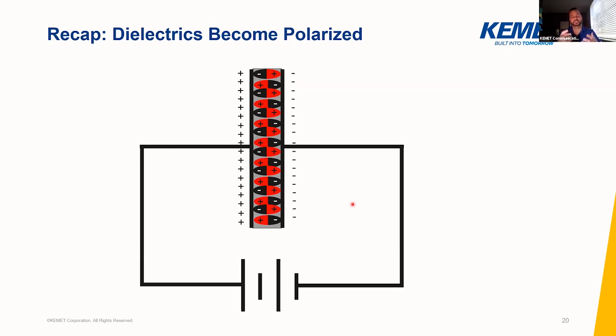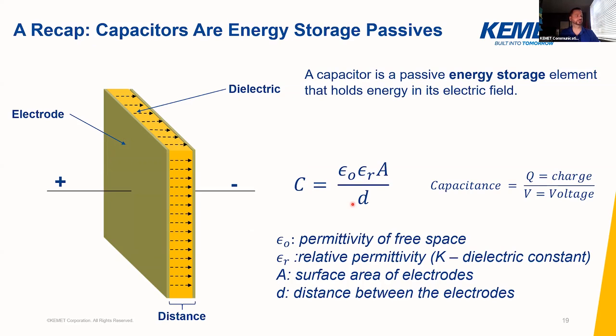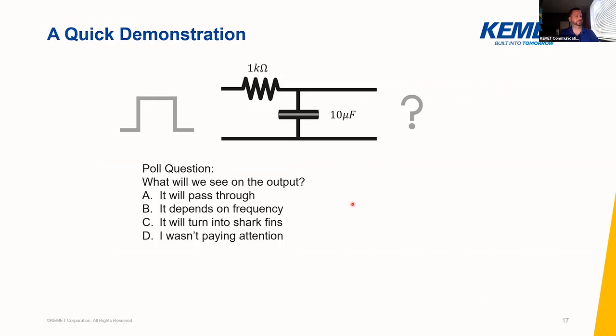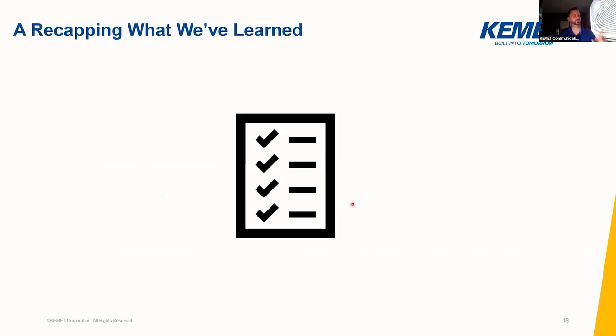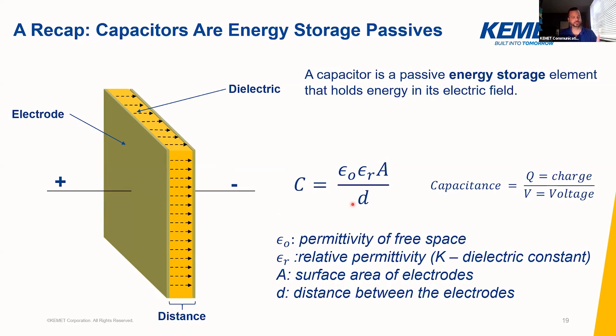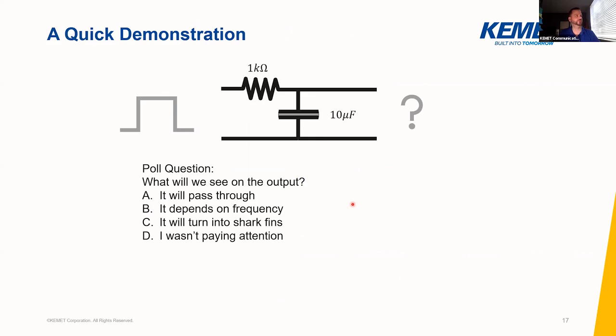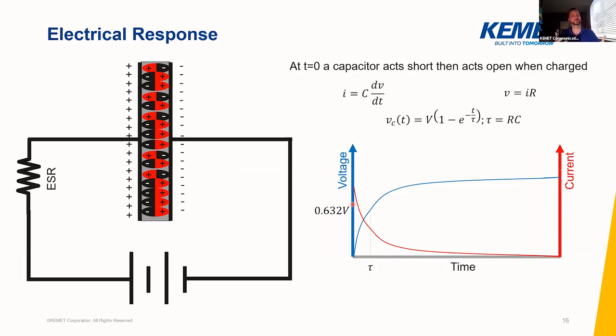That D and A, the distance between the electrode plates and the area of the electrode plates, if you were to know them from your capacitor manufacturer, if they were somehow able to tell you, yes, this capacitor has a dielectric separation of 1 micron and has 17 square centimeters of area, you could use this equation here, and then plug it back into the one here, and then it's all part of the same thing, right?